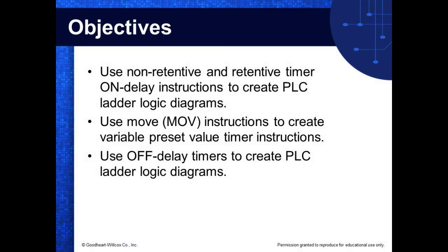So we're going to look at what we call non-retentive timers. First of all, we have two categories: off delay and on delay timers. An on delay timer is going to start timing when the rung goes true. An off delay timer is going to start timing when the rung goes false, which is basically what your headlights do, and my dome lights. So when it goes false is when it does that.